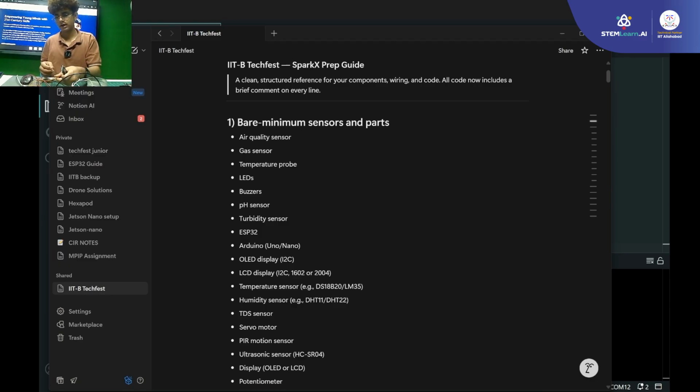I have already got the wires connected. This is ground and this is power pin. First connect them accordingly on the LCD display. Then there's a pin called SDA and SCL. SDA on Arduino is analog pin 4 and SCL is analog pin 5.